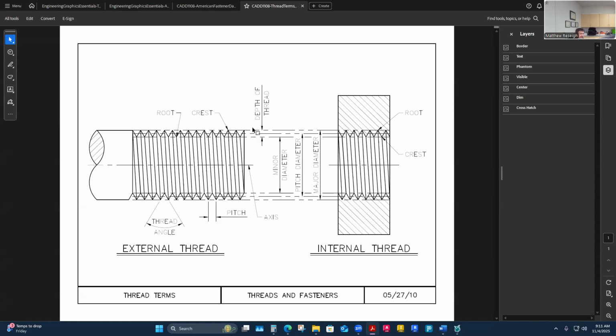And sometimes when I design parts, I like this picture because this shows that maybe this fastener is going to have to thread into this. That's why it's so critical that when I'm designing stuff to accept a fastener, I understand that the hole has to be designed so that it leaves enough material for those threads to be cut, right? If it has to be a threaded hole, that means I start with a very small hole, something in its maximum material condition, and then they can come in with a tap.